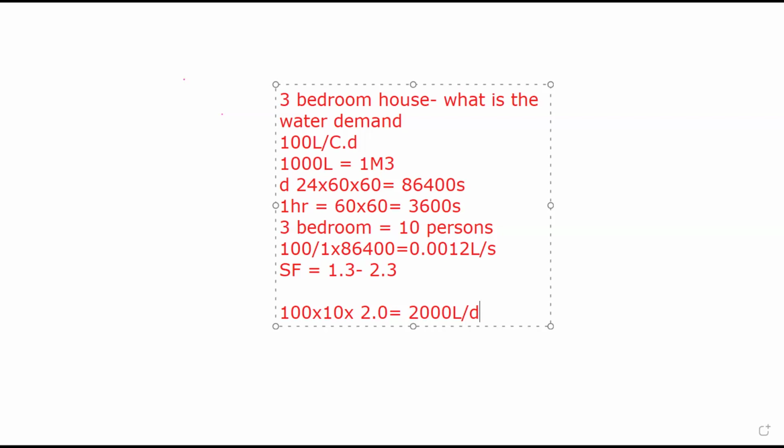If it's the same main pipe that then taps off into the streets, good and fine. But if there's going to be future development at the down end, then the pipe size needs to be consistent so as to accommodate the down end.